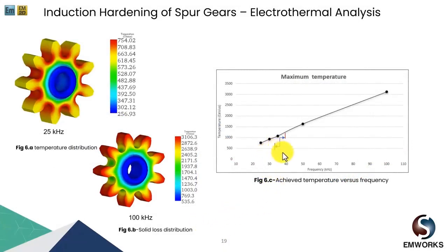For the following temperature results at the first and the final used frequency, we can conclude that lower frequencies are used to heat the gear root, and higher frequencies are essentially used to heat the top tooth surfaces at higher temperature values. So we saw the impact of the frequency sweep on the losses and skin depths. Now, how to select the optimal frequency according to temperature?